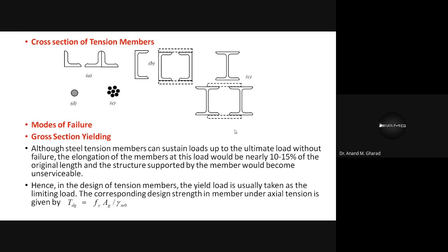Not only for bolts, but we are also supposed to check whether the members in the form of plates are able to sustain all the three modes of failures or not. That also we need to check. So, after providing the number of bolts, whether the bolts are placed in a better order, keeping in view the edge distance, the pitch distance. All these terminologies we have already discussed. I hope you remember all these things. If not, please go through the earlier discussion and try to recollect.